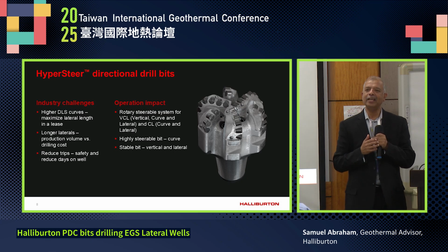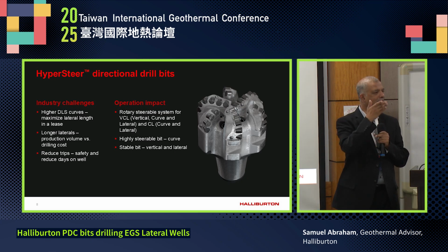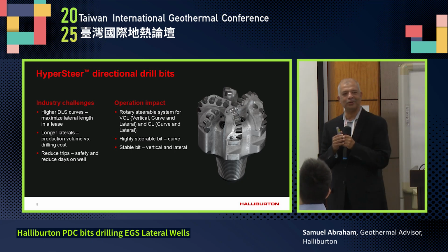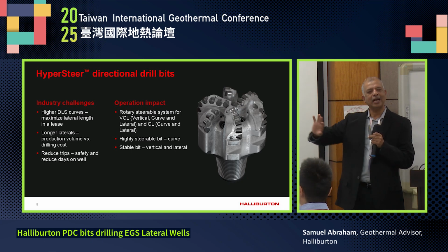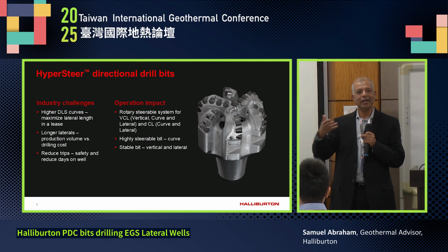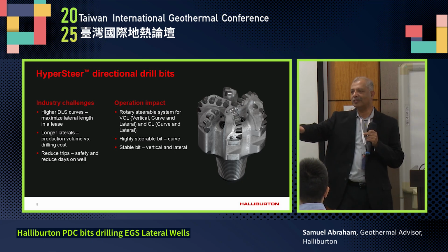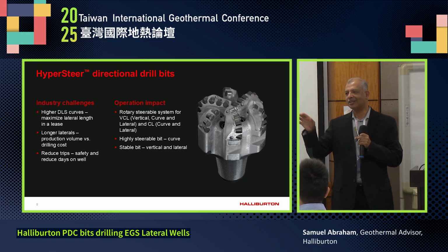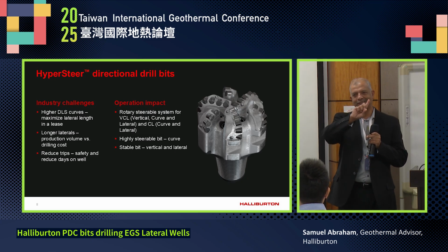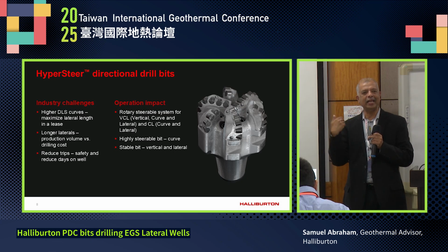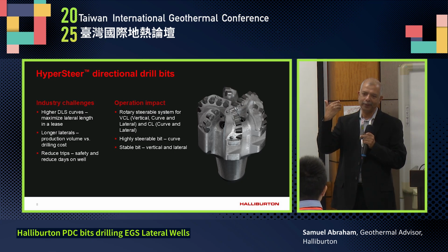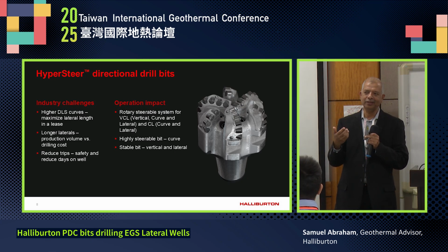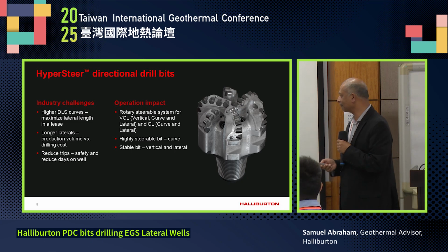you have a problem of getting stuck very soon. I'm sure drilling guys will agree to that. You start drilling the holes, you start losing circulation, your cuttings are building up on the low side of the hole. And very soon, if you have not drilled these types of wells, let me tell you one thing. As a driller, watch your brakes. Watch that gauge on the torque starting to rise up, because these cuttings are piling up behind you. If your cuttings are not transported, you're ready to get stuck at that point.